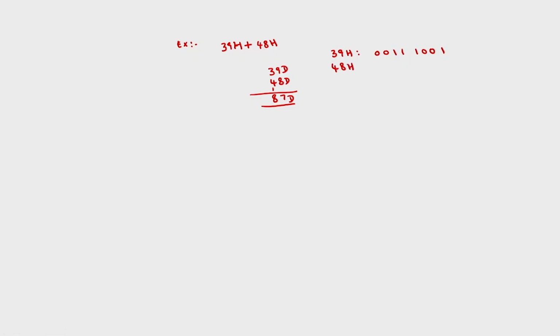it will take as a hexadecimal number. So the corresponding binary is 0100 1000, and it will perform the addition. This is 10010. This magnitude is less than 9 in the lower order nibble, but there is an auxiliary carry flag because there is a carry from the lower nibble to the upper nibble. So the auxiliary carry flag is set.